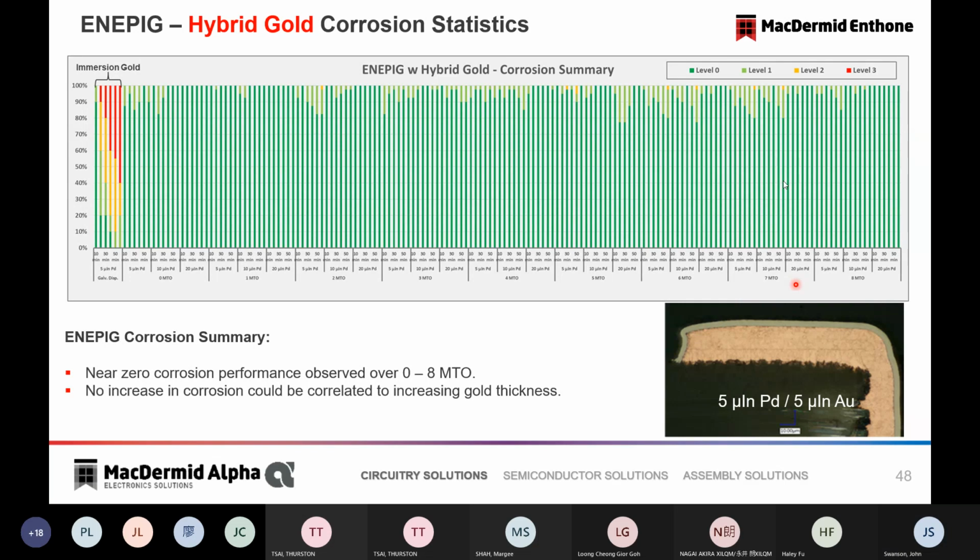So both OSP and immersion silver require some form of protection in that way. They are not designed as lifetime protection agents. They really have been solderability preservatives. But I can say if you do a teardown on some ADAS applications, some radar applications, you will find immersion silver, and you will find some innovative techniques for protecting those surfaces from real exposure.